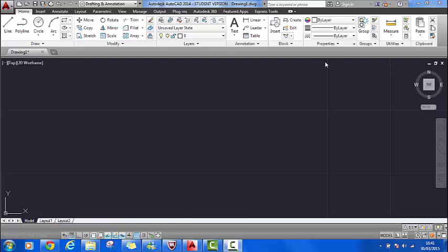In this video we're going to explore the basic elements of the line command, which you can find up here in the draw ribbon. It's the very first command. Lines can be created using polar coordinates. Now, what are polar coordinates? Polar coordinates use distances and angles to describe the position of a point. The distance and angle are made relative to the origin, 0, 0.